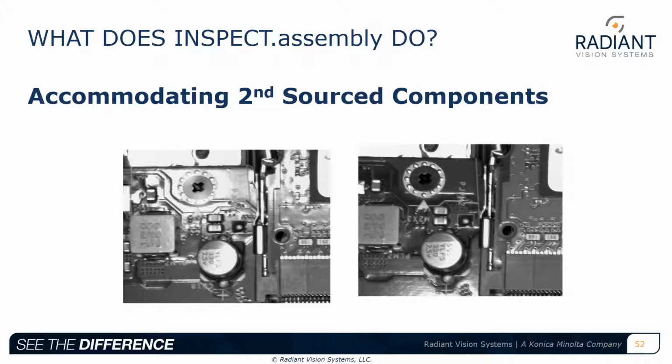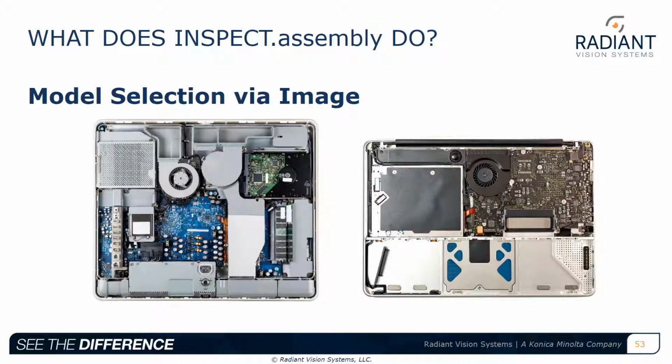The system detects changing components and performs the correct test. In general, specified is a minimum 50% luminance change between components, and all the components need to be tested and registered before the production run. We have the ability to distinguish different model and mixed product using either the smart image sensor or features within the inspection test image itself. Based on the complexity of decision making, additional cycle time could be required.